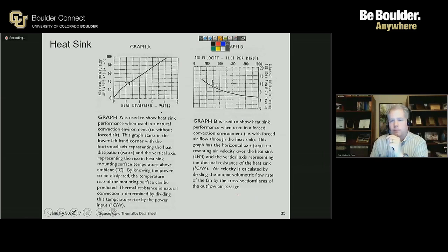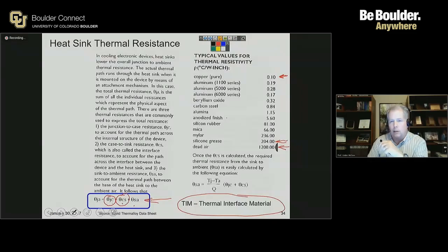Front row: How does mica reduce the air gaps? Is it in a powdered form or some gel, or is it just solid sheets? I'm not sure about the physical construction of that material, but in general, those joints are compressible. If you look at the mica or the rubber and you put them between a heat sink and a package, you typically use some type of machine screw to tighten it, and you're forcing those things in tight contact with each other. That's my assumption there as well.